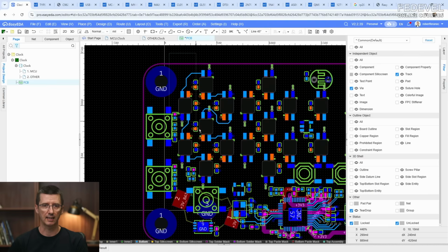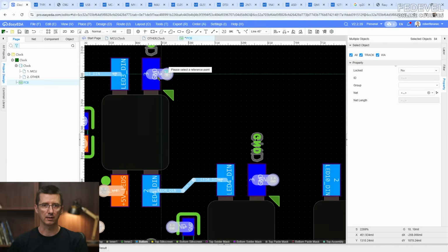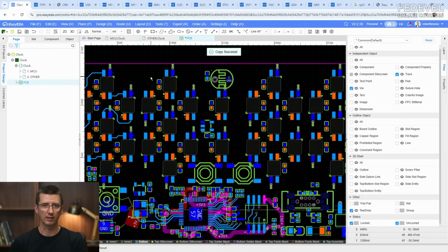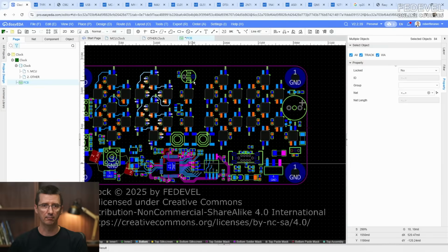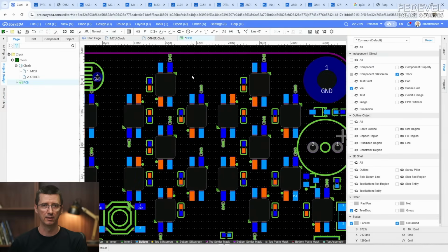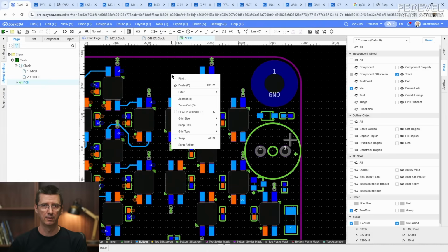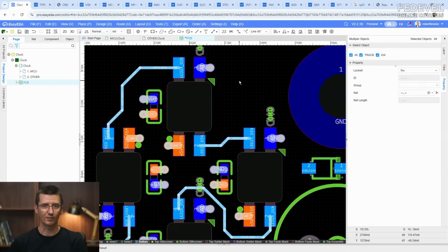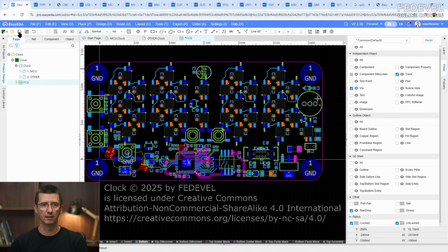We are going to select all these connections what we just created, pick it up in one of the pins or one of the paths, and now place it on the exactly same path, but the second number, third number, and fourth number. So this was really super useful. Okay, if you can copy layout, then you can do it this way.